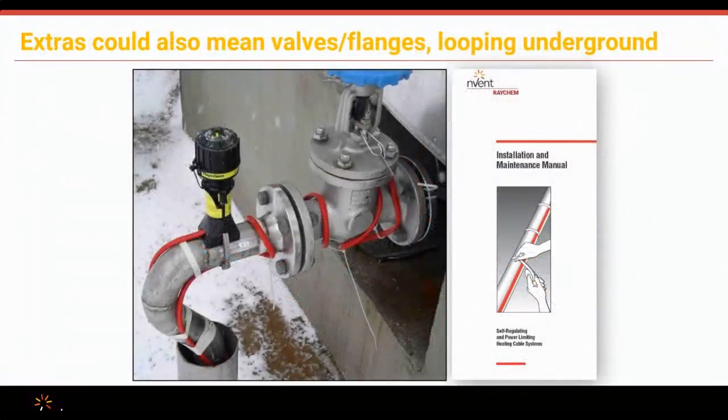Other extras. This is a big one. Valves are more heat loss. So we do have to wrap our heat trace cable around those valves. In our installation guide, we go through very specific steps on how this is done.